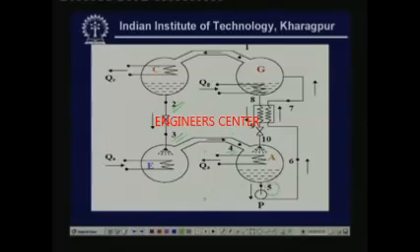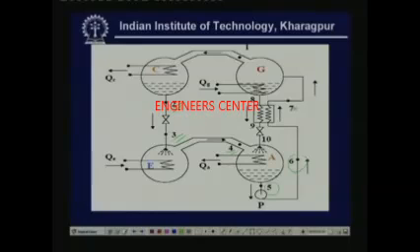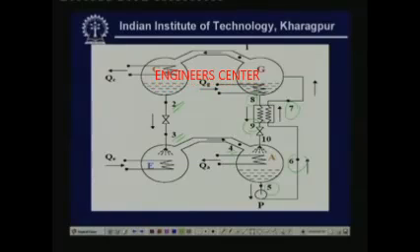Point 5 is weak solution at evaporator pressure. Point 6 is weak solution at generator pressure. Point 7 is preheated weak solution at generator pressure. Point 8 is strong solution at generator pressure and generator temperature. Point 9 is strong solution, now cooled, still at high pressure. Point 10 is the strong solution at evaporator pressure.